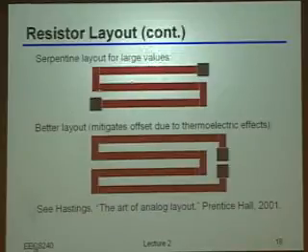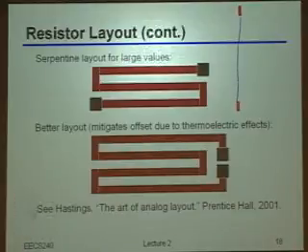Okay, so if we think some more about resistor layouts, there's actually even a whole lot more very detailed things you can start getting into. So just as an example, if you want a really large value of resistance, you typically don't want to do that as a contact there, and some line that would be microscopic on this drawing, going off with this really long skinny kind of wire like that. Typically, it's much more convenient to just do things with a more reasonable aspect ratio, right? So as an example, you may do that by this serpentine kind of layout, right? Where rather than having it run completely in one dimension, you snake it so that you're fitting into a more compact 2D space. Does that make sense to everybody?